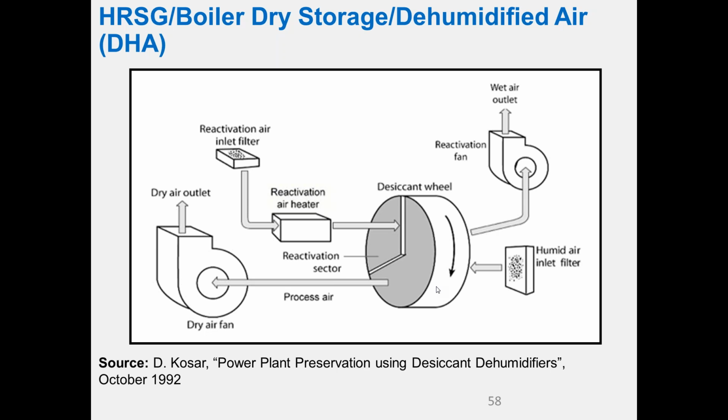So this is really a lot of problems I see around the world is due to poor layup and storage, where people have initiated a whole bunch of corrosion problems because of the way they've stored the plant. And things like if you get pits in certain locations, the pit, eventually it'll cause a through-wall failure on its own, and that's a problem. But the problem is you've created an irregularity in the surface, and there's a whole secondary bunch of corrosion problems that occur because you get cracks that then form from the pit when you put the plant in service.